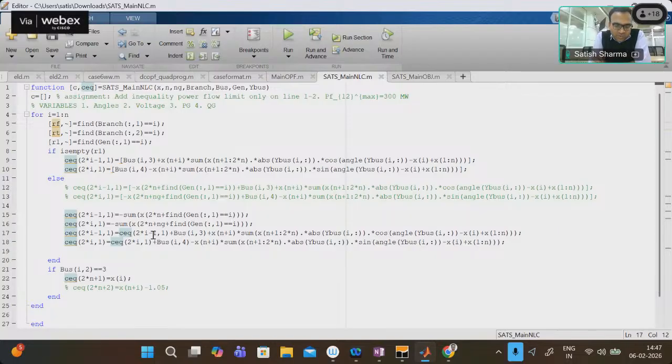If there are a lot of combinations, and it being a non-linear problem with many combinations, then that problem will become NP hard. If we try to incorporate storage in the ACOPF problem, then time complexity will also be added. As long as we are not considering unit commitment related constraints, which add that complexity of time, OPF can be solved for each hour separately.